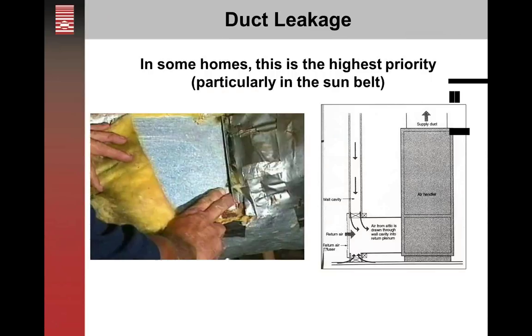Duct leakage also is an important aspect. For example, in the image on the left-hand side, you can see how it was never really completed with the connections from one transition to the next in this duct system. The hole is large enough that this particular person was able to stick their finger through. You can also notice on the left-hand side of that image, where the insulation is dark, that the insulation is now acting as filter media instead of true insulation.